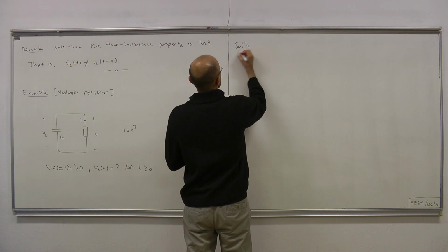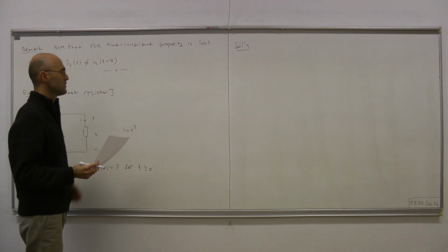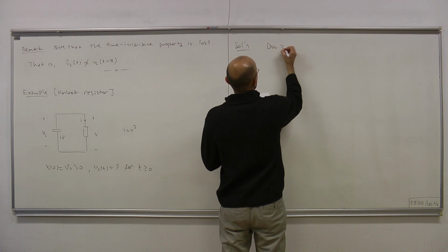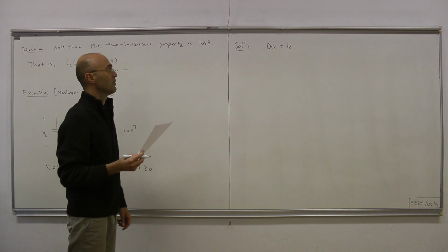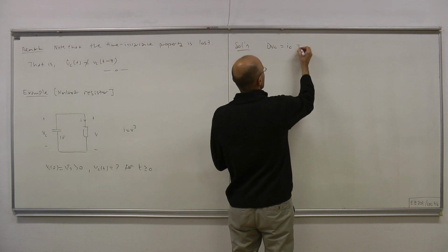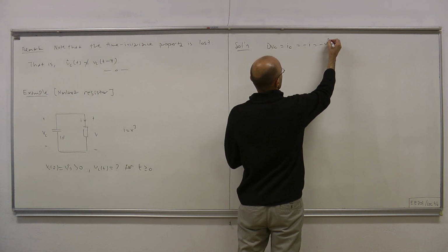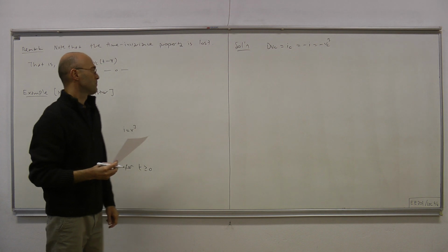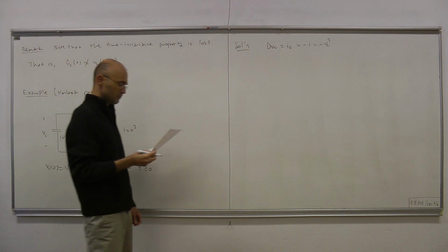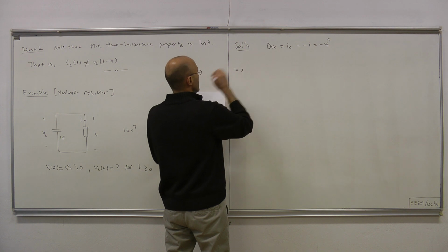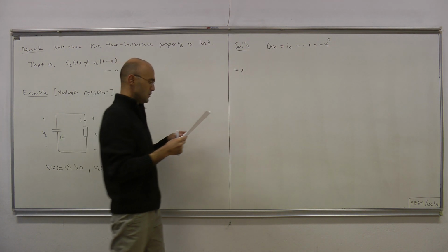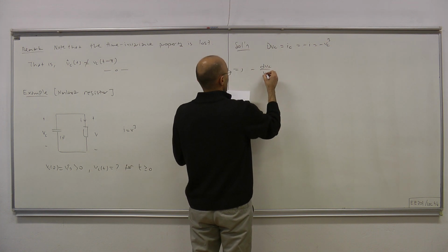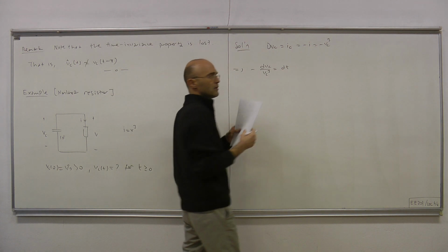Okay, so again, let's start from the terminal equation of the capacitor and obtain the differential equation. dVc/dt equals IC, because the capacitance is 1 farad. That's minus I, and that's minus V cubed, and that's minus VC cubed, because V and VC are the same voltage. Therefore, and this operator is d over dt, hence we can write minus dVc over VC cubed equals dt.